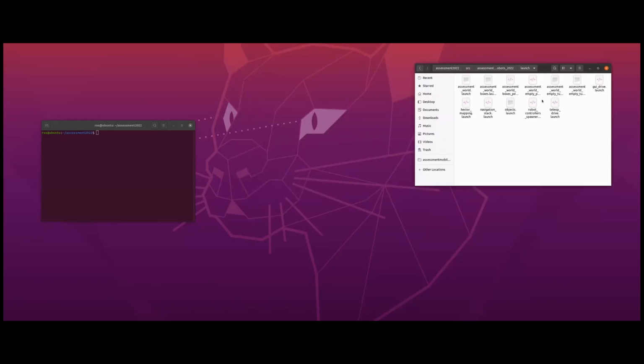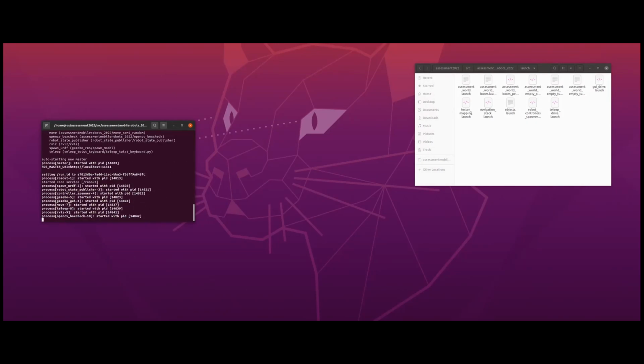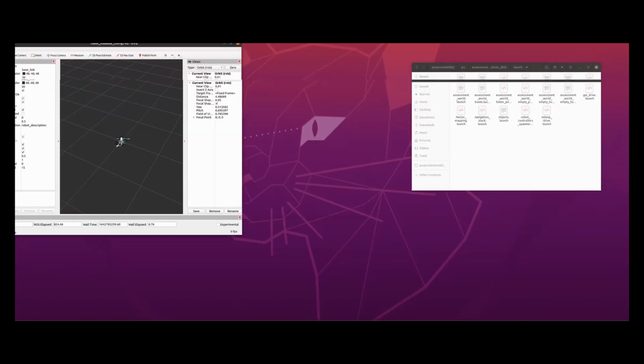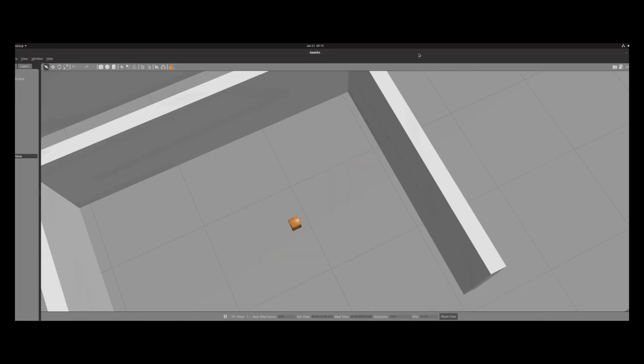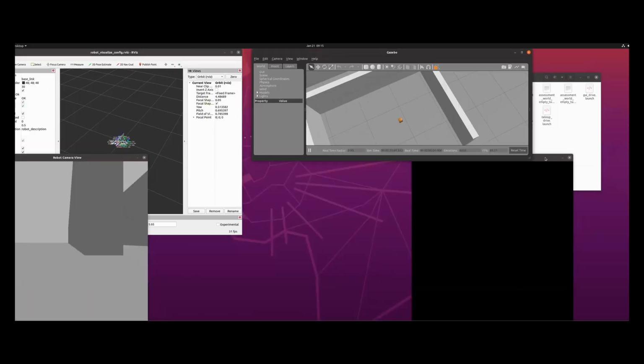different modules. So let's start by launching the Teleop Drive module, just to show how everything is. So roslaunch mobile_robots teleop_drive. We'll launch this. This will be launched with RViz and Gazebo at the same time, as well as computer vision.